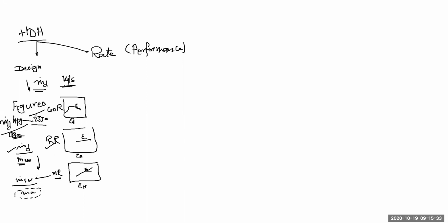And then basically this is how we get the basic components, and there will be another parameter if I need to calculate, for example, the surface cross-sectional area of the humidifier. Then we use m dot water over area as the mass flux in the humidifier, and we pick a value of 1.5.